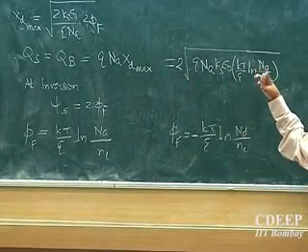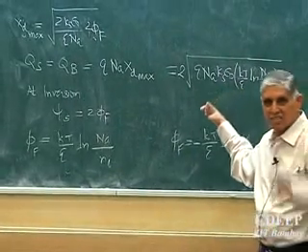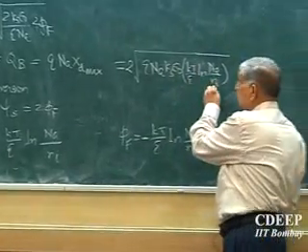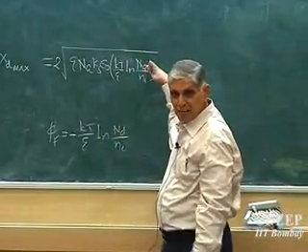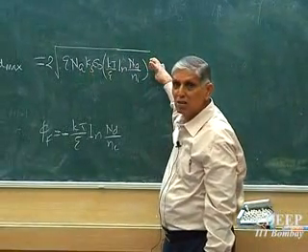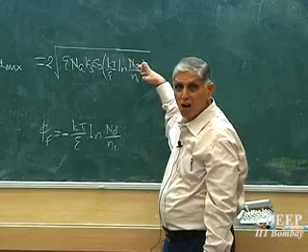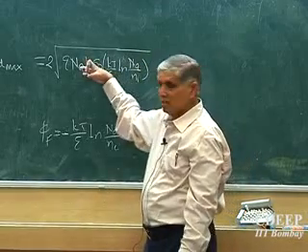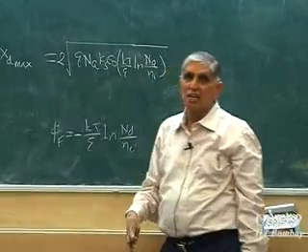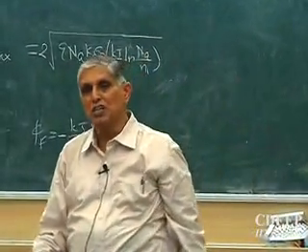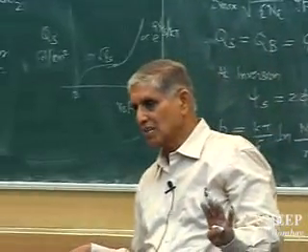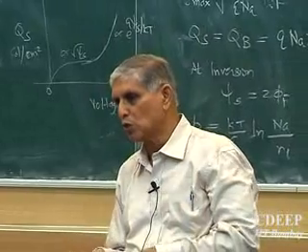So this is the bulk charge. Is that correct? This is the bulk charge. It is a function of Na by Ni. Na, how much is doping? Here also Na, but this term is smaller. Why? Because of the logarithmic term. This is directly root of that. So one can always say the bulk charge will increase proportional to doping. Root of that, but proportional to doping.